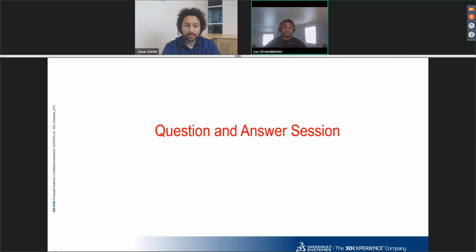Some requirements for shutoffs, you have to have at least 3 degrees. Light textures, you should have 3 degrees. For heavy textures, it is recommended to have 5 degrees or more. So a last note to that is if you have a part that can't, or a face that can't even handle 1 degree, then specifying any draft, even half degree, quarter degree, would be better than not having any draft at all.